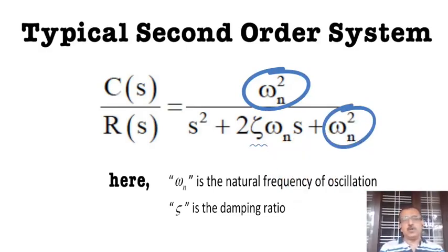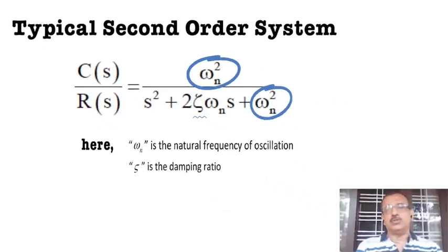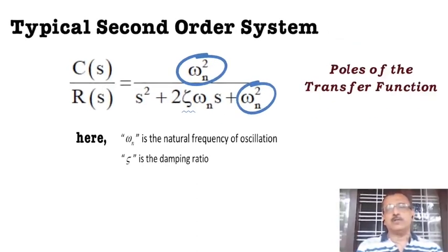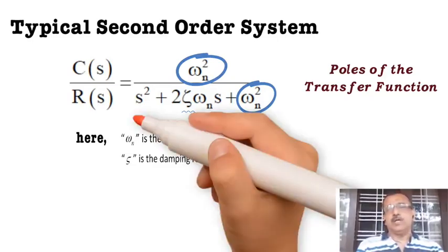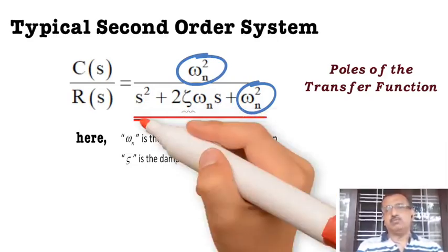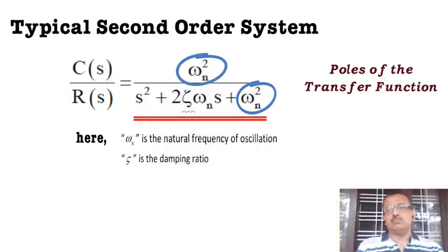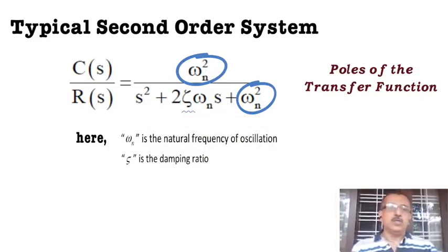And I have told you in passing about one technical term which will come quite often, called the poles. Poles of the transfer function correspond to situations where the denominator becomes 0. It's very important, so that's why I'm writing it slowly. So this is our transfer function.